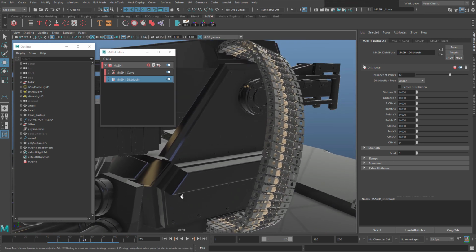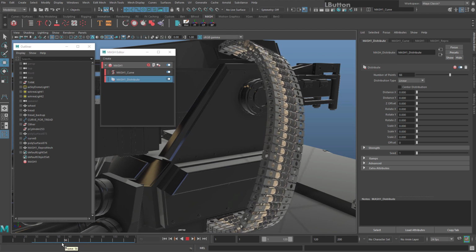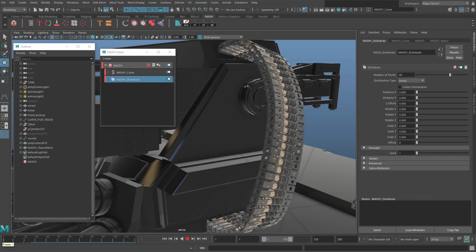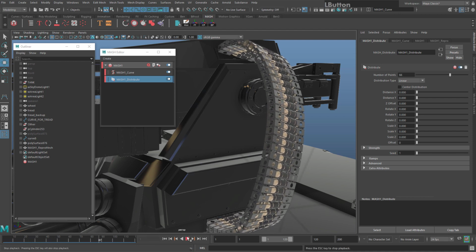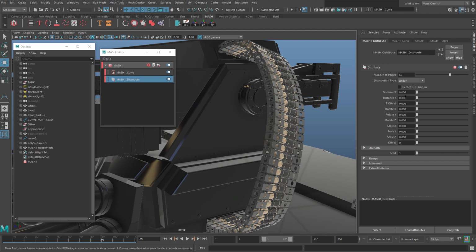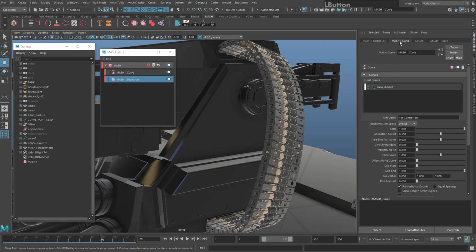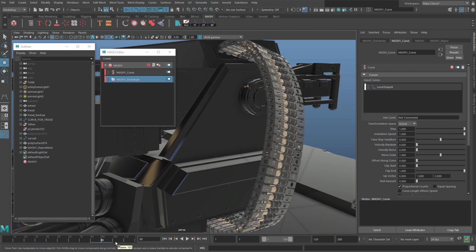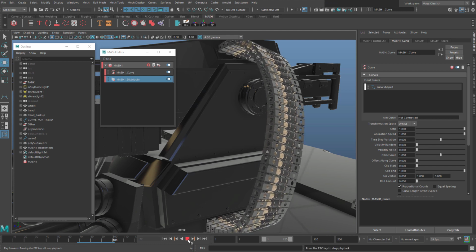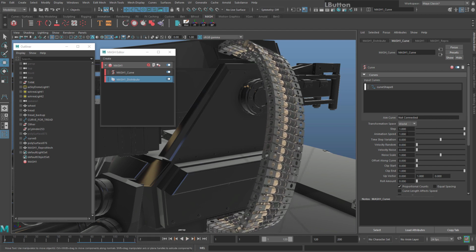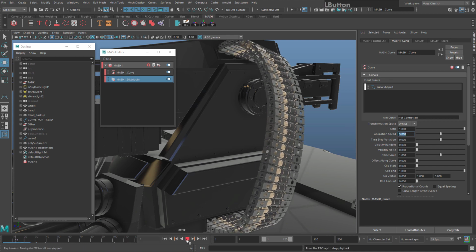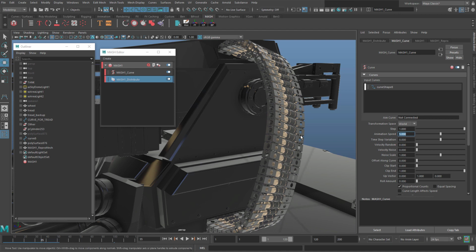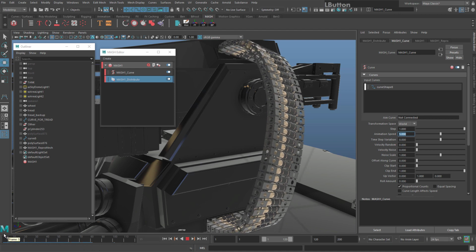The magic trick on this is it's actually secretly animated for you as well, which is awesome. So if you just hit the play button at the bottom, you can see the speed that this goes at. That's obviously quite slow for bullets. So if you want to change the speed of this, just simply go down to your Mash 1 curve and increase the animation speed. The highest it goes on the slider is to 1. And if that's still too slow for you, then you can overdrive this value, so maybe to 5. You have to type it in to overdrive the value and then hit play and it will go. If you make it go too fast, eventually you just won't see it spin at all. So do what you think looks good.